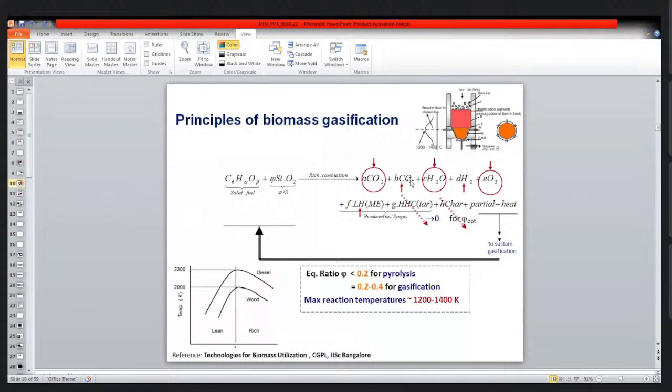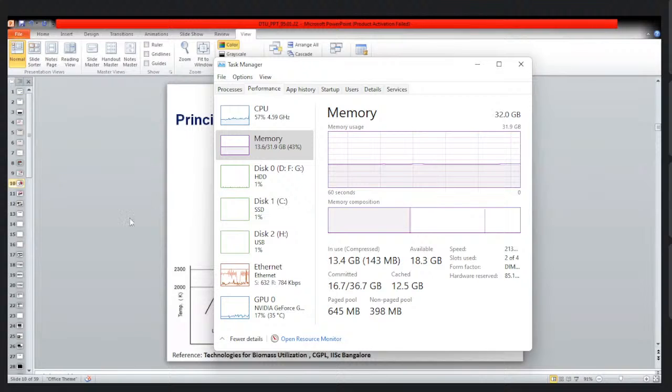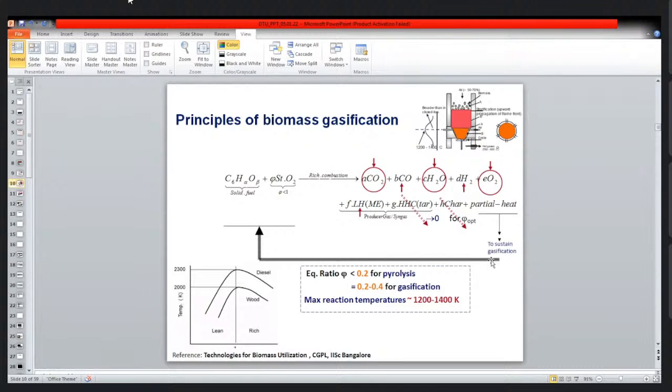Heat is generated partially because the fuel is not converted completely into carbon dioxide, and H2O is also converted into a hydrogen component. So the heat released is relatively less than in complete combustion. We understand that. And then some part of the heat is also required to sustain this combustion. Okay, and the remaining gas comes out from the system at a relatively high temperature.